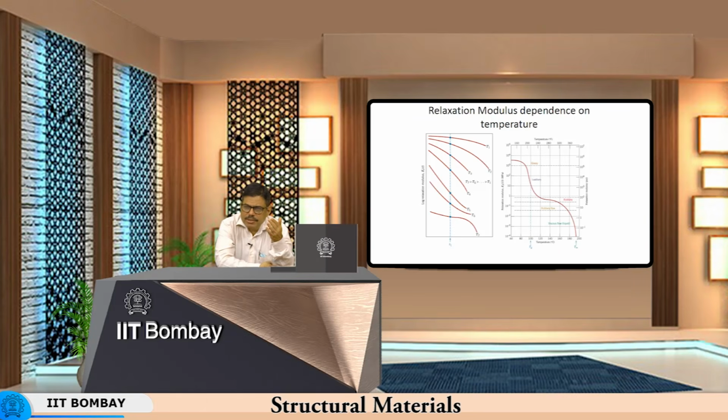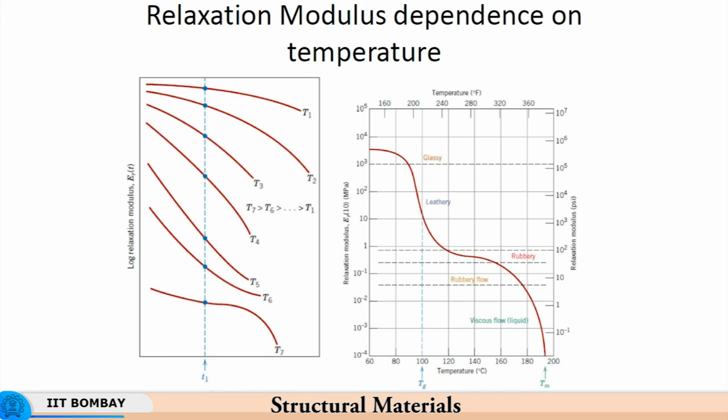In case of metals, you don't have any viscous flow, due to which you always have Hooke's law being followed. Even if you increase the temperature, the equilibrium spacing between the atoms increases, and therefore there is a linear expansion, the slope of the equipotential curve decreases, and therefore the Young's modulus tends to also come down. So the material becomes more compliant, right? So the rigidity, or the Young's modulus of metal